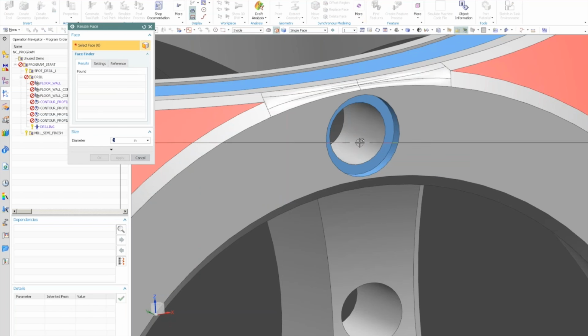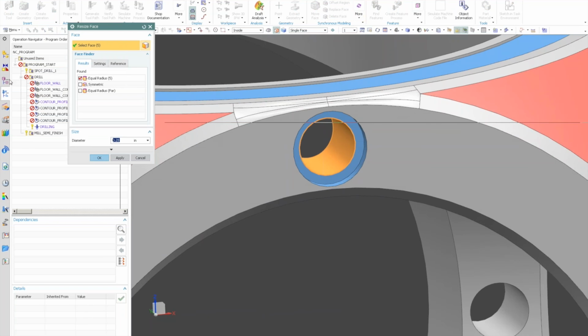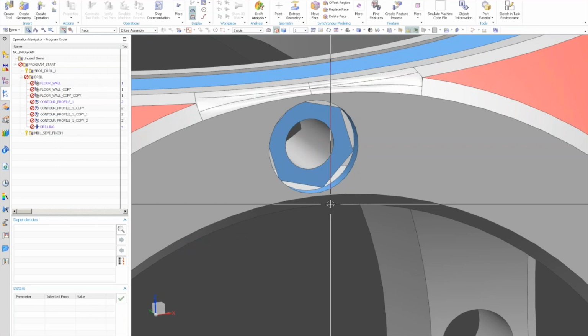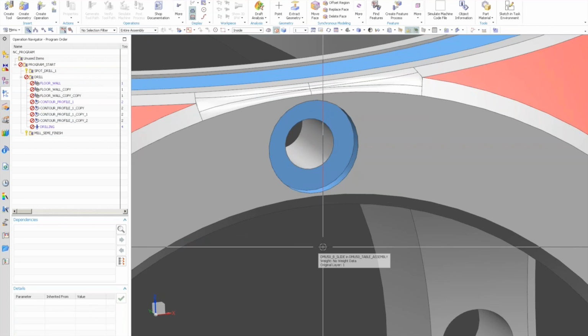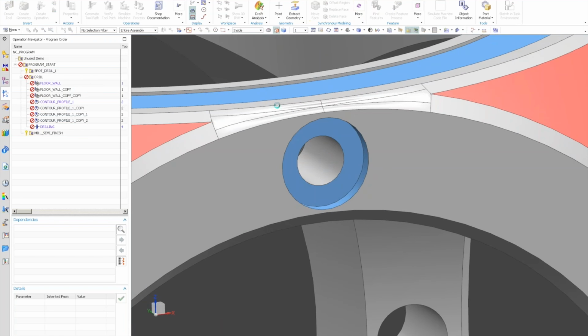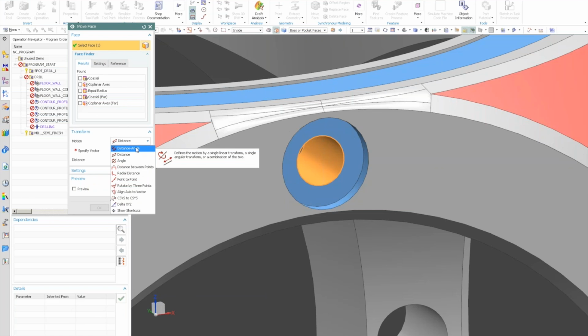So I can resize, whether this was a STEP model or a Parasolid. Right now, this isn't something that's been modeled in NX. I'm doing everything on a dumb solid. This resize face recognizes the current size, and I can change the size of the hole. Right now, feature-based is looking at changes, and that's why you saw that update there. But I can go and, let's give this face some angle here.